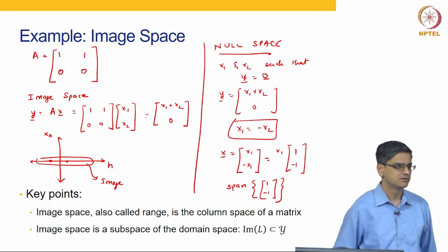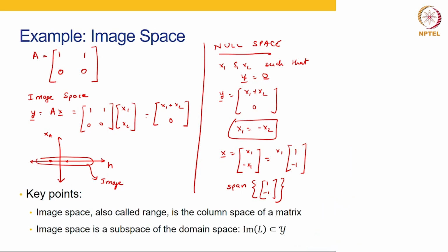What does that mean? That means if you increase flow rate F1 by 1 liter per minute and simultaneously decrease flow rate F2 by 1 liter per minute, your height is not changing because the net flow rate in has not changed. Your concentration is not changing either, because the purity of stream 1 and stream 2 were the same.